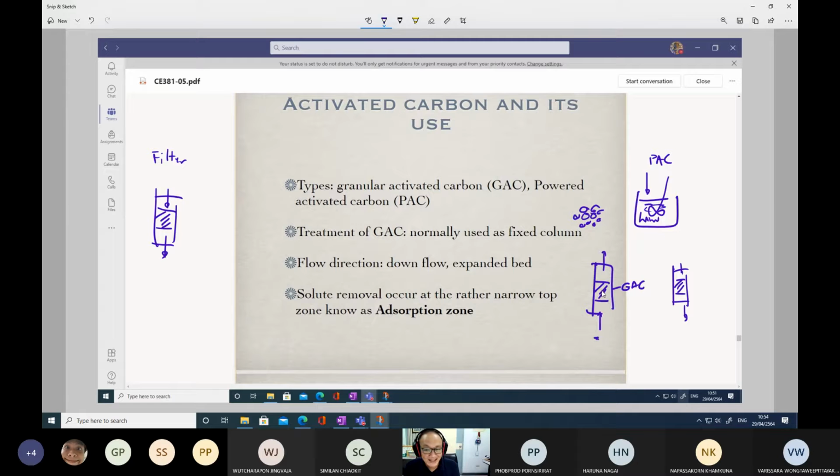The water inside the pores of the adsorbent will always be flooded, and this enhances removal efficiency. But with downflow, particles sometimes move out or escape from the adsorbent layer, so upflow is actually better.